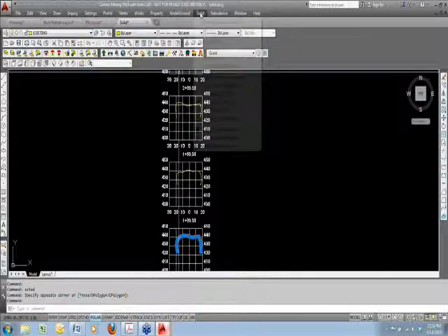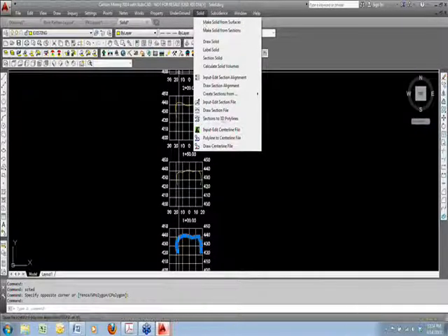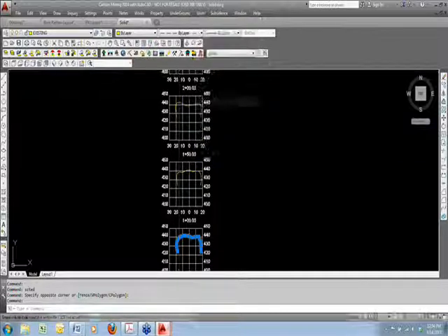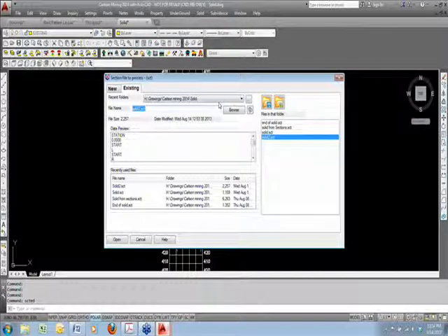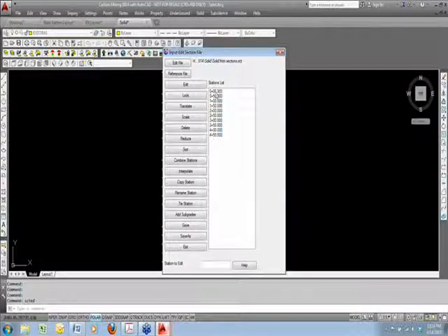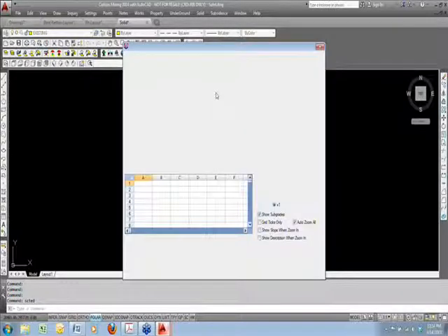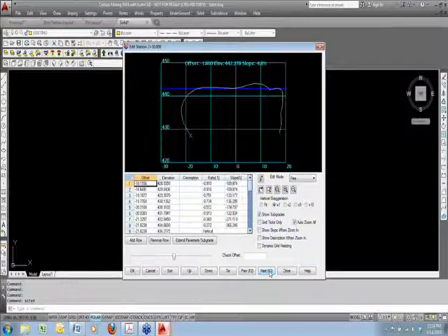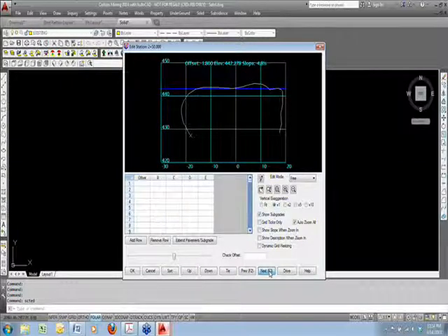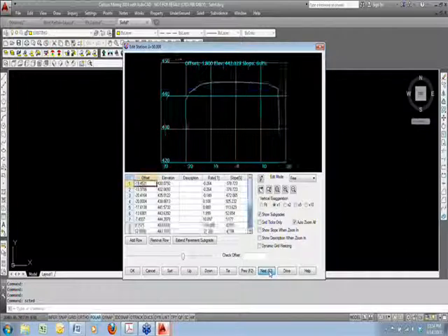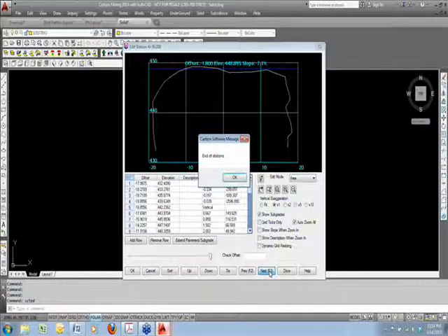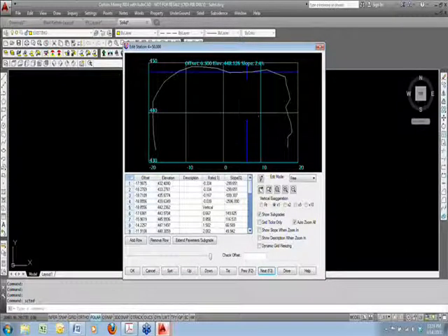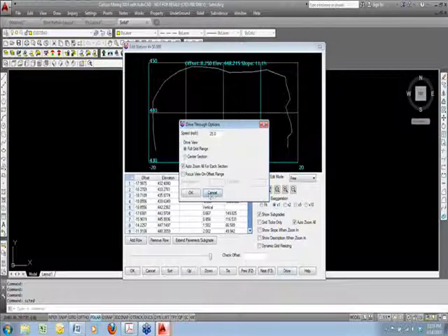So we'll go ahead and do that input edit section file one more time. And that would be solid from sections. There's station 0 to 4500, and I'll just go next all the way through it. You can see now the sides are not vertical. It does handle the overhangs, the circular cavities. That's not a problem. And so I've made then these cross sections, just an SCT file. Okay, exit.